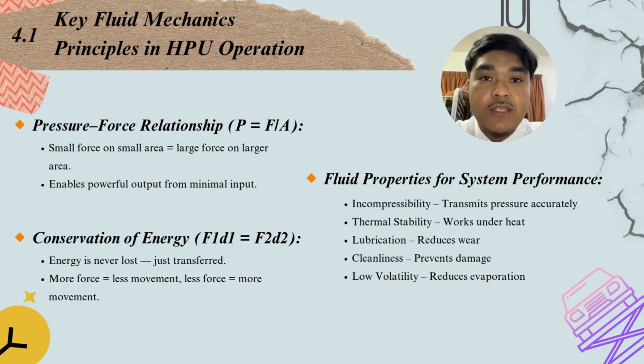Lastly, fluid properties for system performance. We have incompressibility, which transmits pressure accurately, thermal stability, which works under heat, lubrication, which reduces wear, cleanliness, which prevents damage, and low volatility, which reduces evaporation.